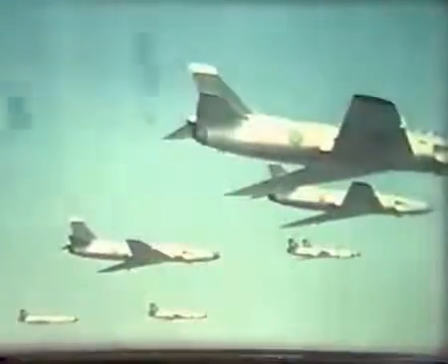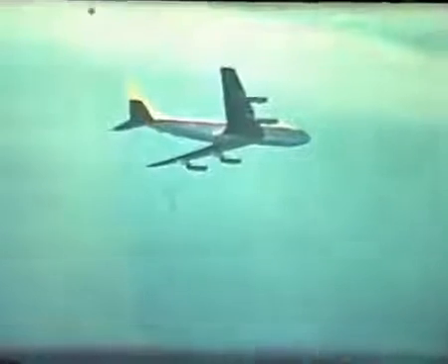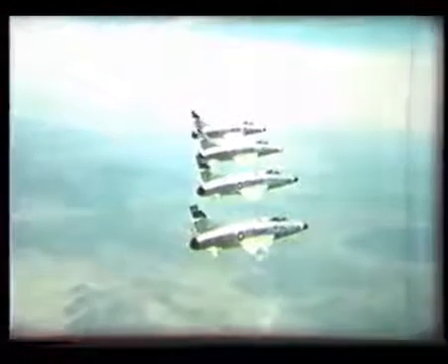Sweep back, like thin wings, brings its own problems at low speeds, such as tip stalling. So designers must compromise between high speed and low speed requirements. And aircraft designed to fly near the speed of sound use thin wings together with sweep back to obtain a high critical Mach number. If the swept wing is too thin to contain the engines, they can be mounted externally in pods. All these improvements in design are reducing shock stall troubles in the difficult earlier part of the transonic range.